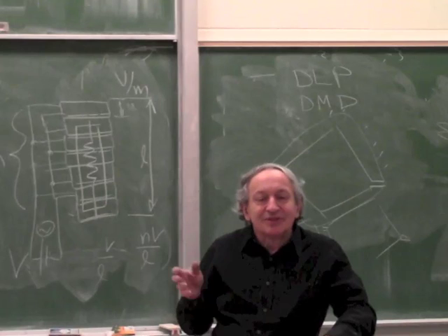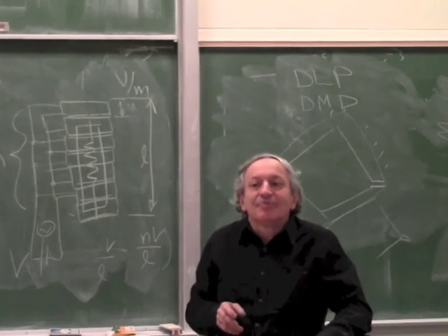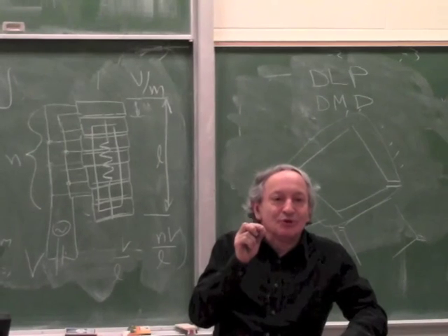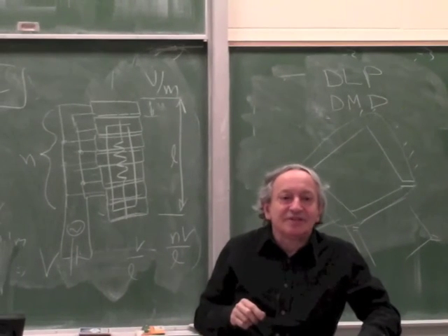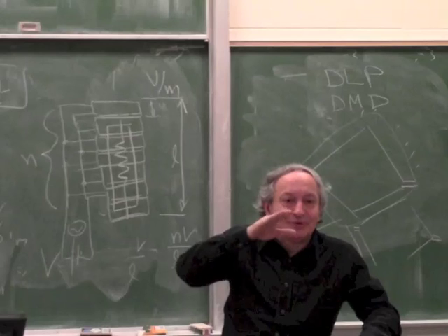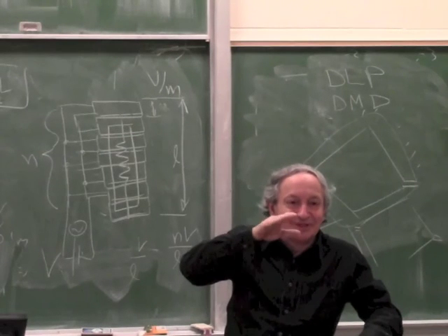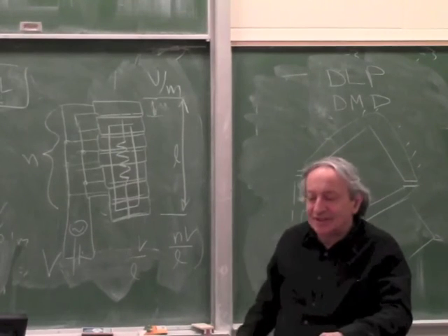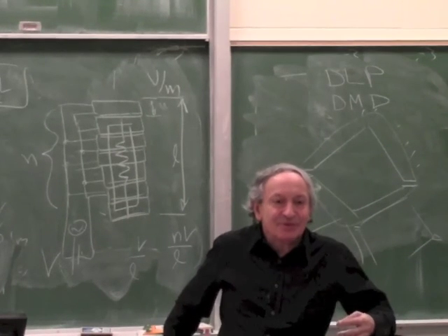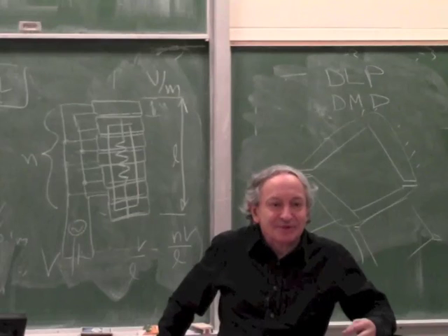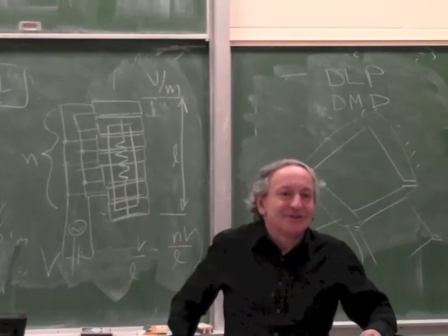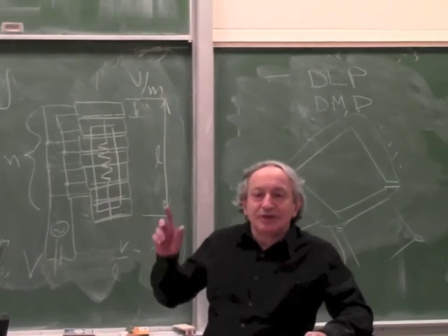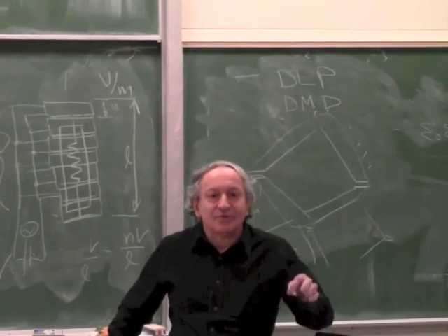Okay? So both actuators have some limitations at high frequencies, but piezo is very nice and elegant because you can make very controlled small motions. So if you have a scanning tunneling microscope where you want to move the needle nanometers or picometers at a time, piezo is very nice. So for very small motions, piezo is very nice, but when you start building a big actuator from piezo, you realize right away it's no better than a magnetic actuator because of all these problems. Okay, we'll cut it off here. I'll do a quick refresher on piezo Thursday and talk about some other actuators.